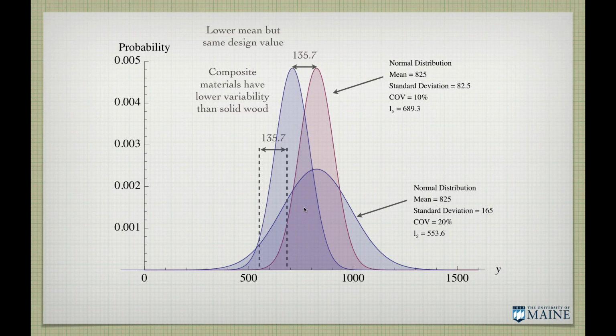Which is a reason that in grading, sometimes plants can go through and regrade material. If you can pull out those couple bad pieces and retest, you can get a much higher value. In fact, that was done with this Norway spruce testing. There were some samples that were very low in properties. And we said, well, why is that? The graders went back and looked and said, oh, that really wasn't a number 2, that was a number 3.